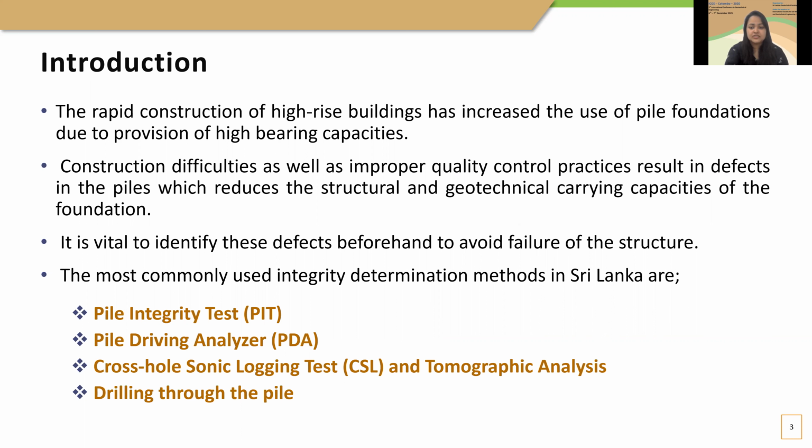But the construction difficulties and improper quality control measures undertaken can result in defects along the pile shaft, which reduces its load-bearing capacity. So it is important to recognize the integrity of these piles before construction of the superstructure. And among various testing methods available for integrity testing, the pile integrity test, the pile driving analyzer, cross-hole sonic logging test, and coring of the pile can be considered as the most commonly used methods in Sri Lanka.